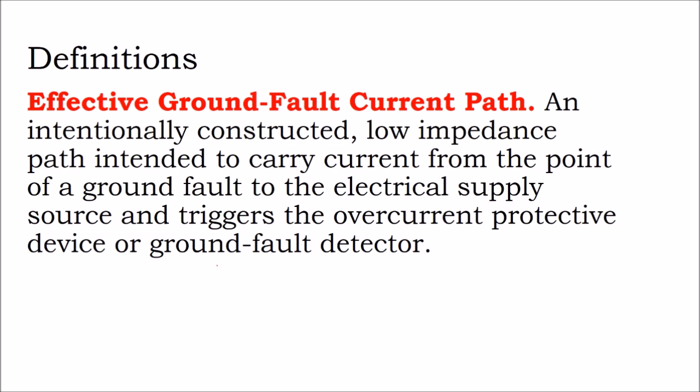So maybe it was that the metal building wall did not have an effective ground path to ground. Maybe the bolts that went into the concrete were considered to be the ground path, but they were never tested, and concrete does not have the resistance that you think it does. So maybe the side of that metal building actually was not grounded.